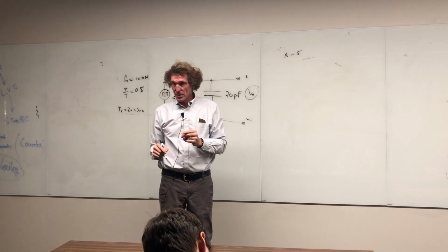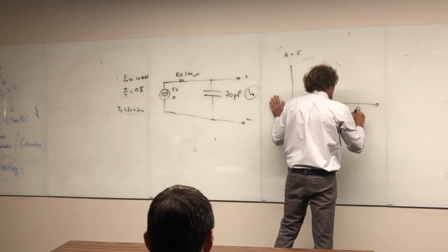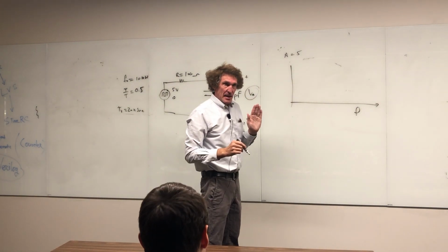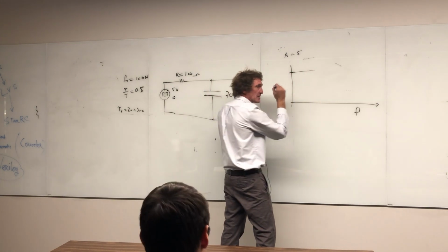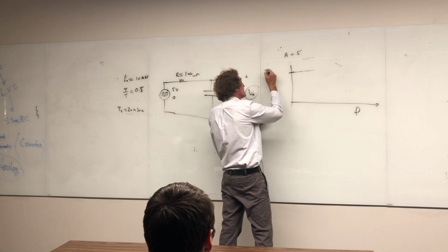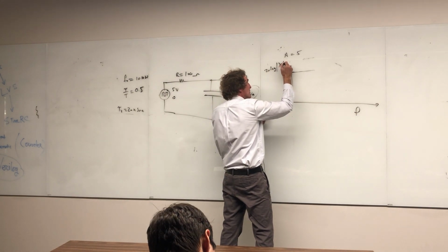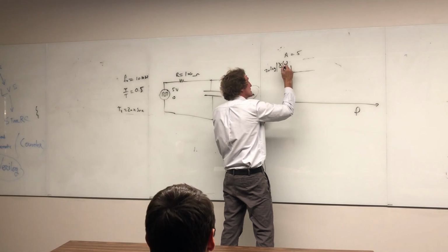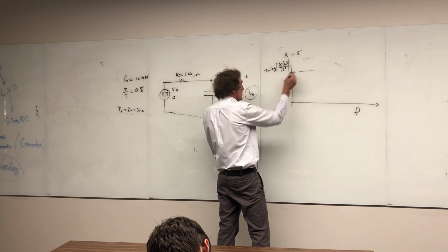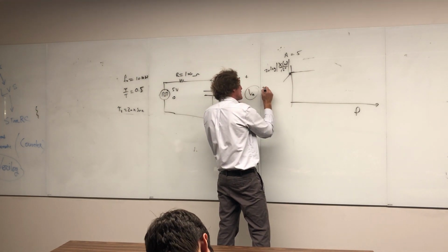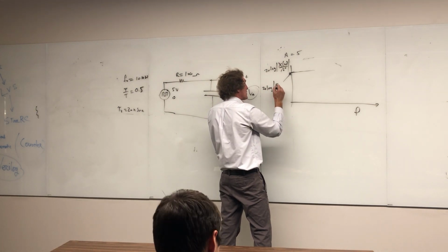Second thing I do is sketch the waveform, and I'm going to do this in the frequency domain, in F, right here. And now what I do is come here, and we're going to enter flat right there, because this is the input. This is going to be my 20 times the log of the magnitude of X of omega, think of it that way, over 10 to the minus 6, so it's in dB microvolts here. It comes in, and this value is going to be right here. This flat part is going to be 20 times the log here of the magnitude of 5,